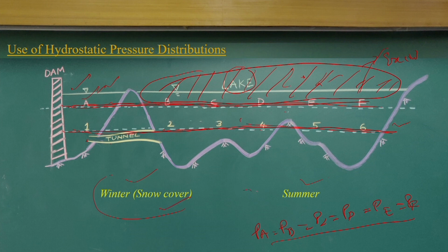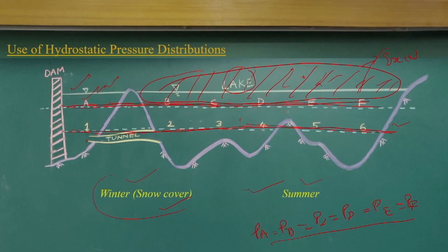So, these are very simple conditions we are talking about. It is a very complex problem if your fluid is in static conditions. We can simplify the problem as if it is connected through tunnels or tubes, which is what we will discuss in manometers. We can consider any horizontal surface, and on that surface the pressure is equal. That is the condition we consider to solve many hydrostatic fluid flow problems.